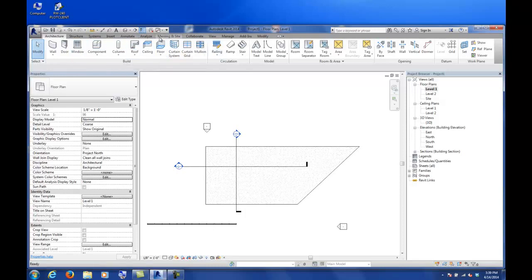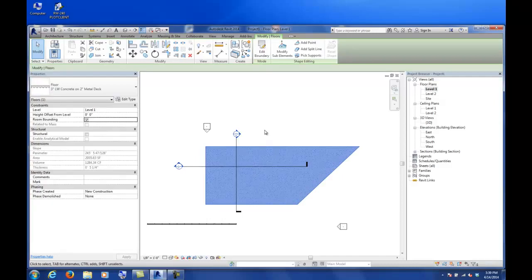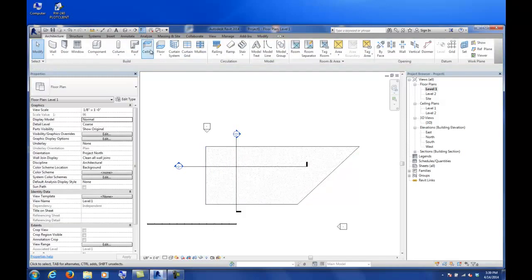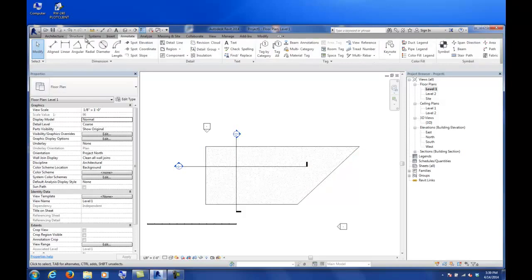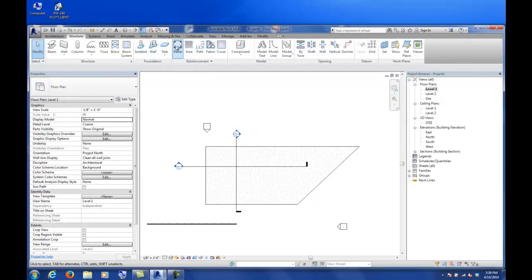Would I just draw the two floors so that I can split the floor plate so that I can get an edge that is running in the correct span direction? Yes, you could do that. But typically, I haven't looked at your structural system, but we end up with cantilevers around the entire edge of the floor plate.